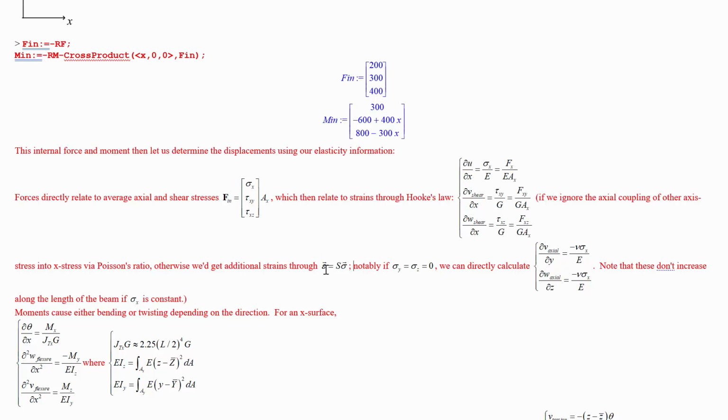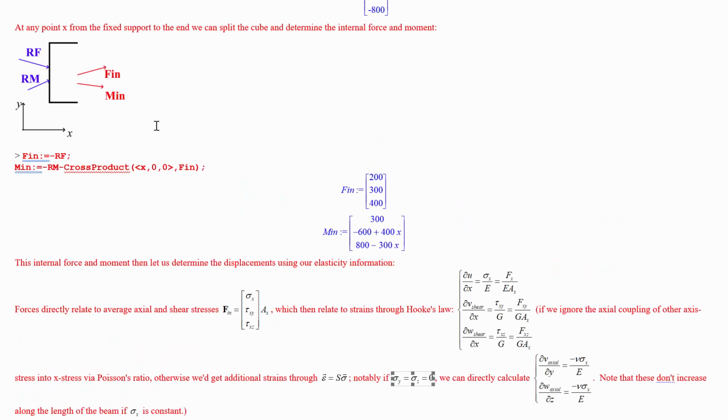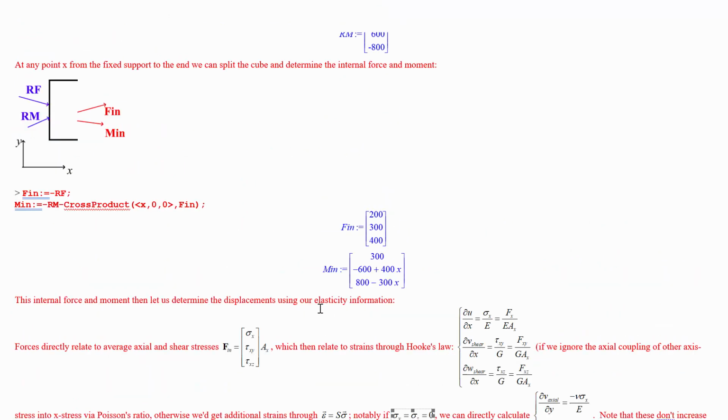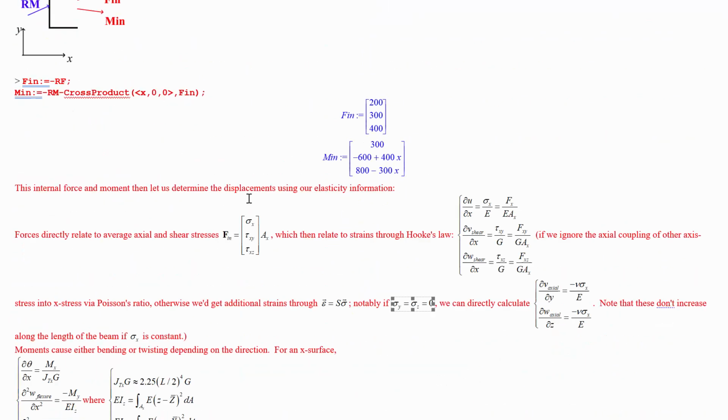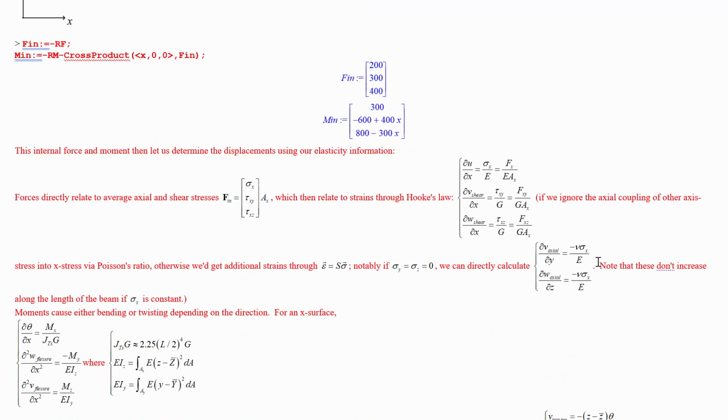Really, we should say that the normal strain that shows up, due to some normal stress, is coupled to it by the compliance matrix, and that gives us, if the other stresses are zero, so if it's free in y and z on these cross sections, then we can use that to figure out that we have an axial source, a normal stress source of displacement in y and z that are modeled through the Poisson's ratio and the x stress.